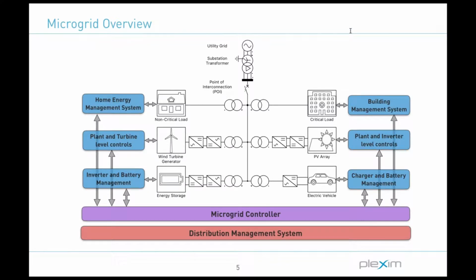Looking closer at our hypothetical microgrid, we'll see that there's a range of systems from conventional electric loads to several types of distributed energy resources, or DERs. Each one of these systems has its own local controller and may have several layers of controls. For example, if we consider a small distribution-connected wind farm, there'll be several turbine-level controls, so DC bus regulation, rotor and grid side converter controls, as well as park-level control loops that may regulate the voltage and frequency at the point of connection. There'll also be, say, protection systems, and then there's this communications infrastructure that links all of these systems together.